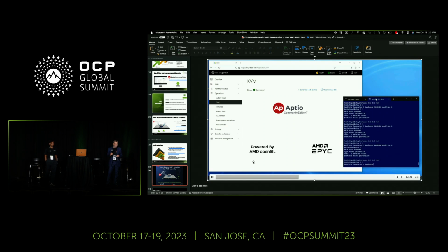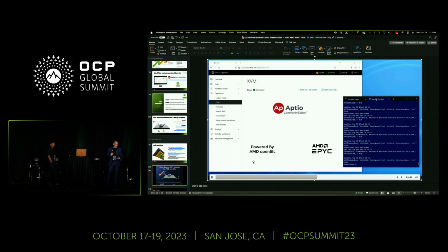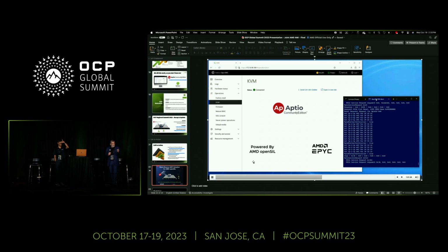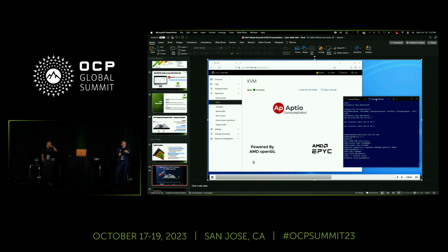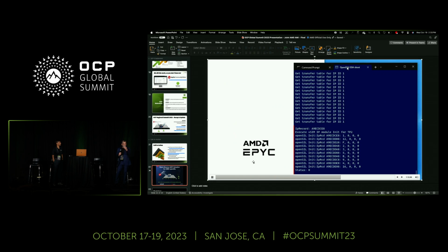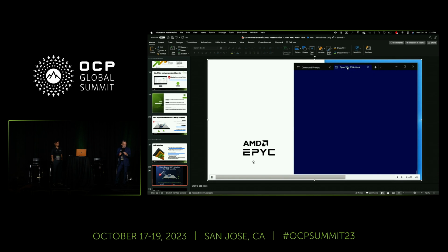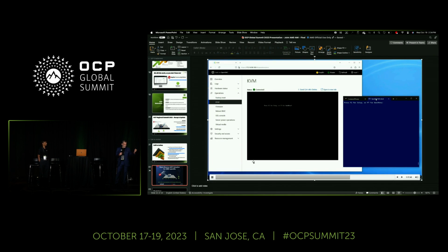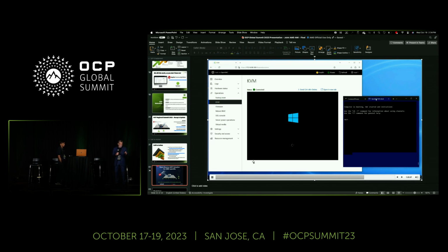That's your platform reference firmware that we supply for the CRB platform, and then you can modify it to suit your platform netlist. If you do not want USB, you can disable it there. Even the CBS options, for example the BIOS setup options, are a responsibility of the host firmware. So those settings come down when the host firmware is initializing the OpenSIL using either the XPRF library or the main library. When it is coming down, the arguments are passed through those APIs. So hopefully that answers your question.